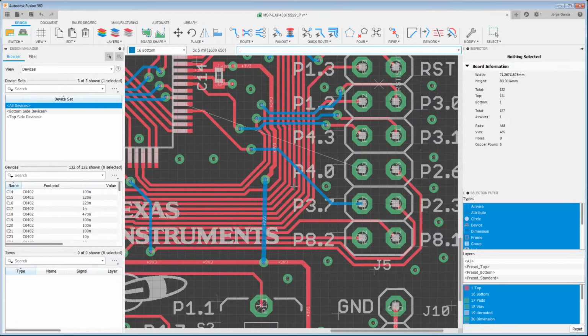Good tip on bends. Do you need to hold down Control to keep ortho mode active, or does it work as a toggle? No, you have to hold down Control. It's not a toggle. Okay. Be nice to be able to import KiCad schematics into Eagle. Thank you for that suggestion. That's something that we do at some point want to address, so thank you for that.